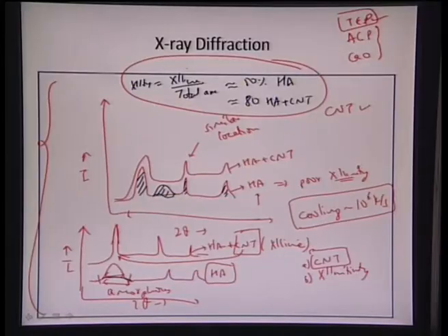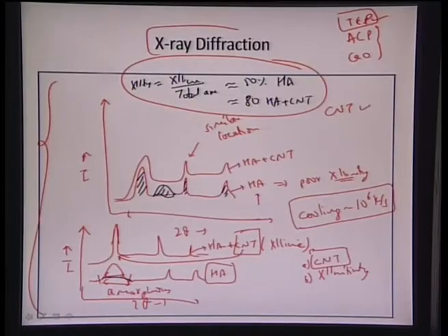then achieving much more crystallinity of the hydroxyapatite in the presence of carbon nanotubes. And at the same time, we don't see any CNT peaks in the X-ray diffraction, because the overall hydroxyapatite peaks are much more dominating, and depending on the concentration of CNT, they may not appear. So that is the overall deal with the X-ray diffraction.